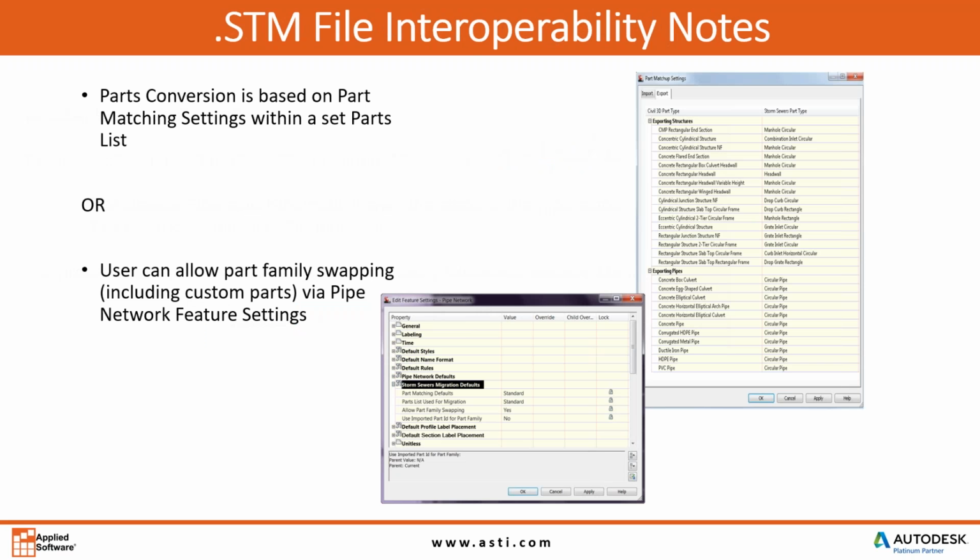And the other thing that I wanted to make reference to was this idea when you're moving data back and forth from Civil 3D. There are a couple things you want to be able to recognize in 2018 from 2015, or even a standalone version of HydroFlow in SSA. There are some HEC-22 inlets that have been addressed in terms of working with inlets and gutter spread. So this parts conversion is based upon moving data from the hydrology programs into Civil 3D and back and forth.